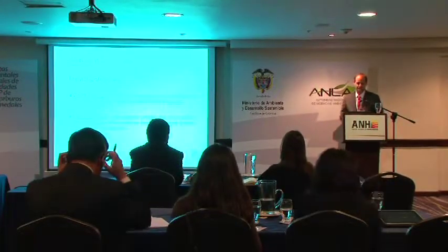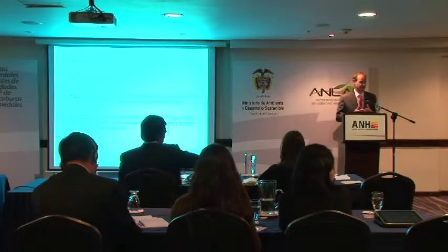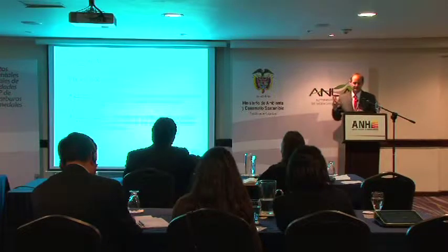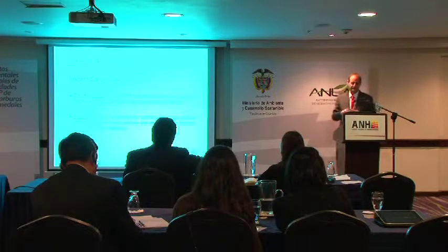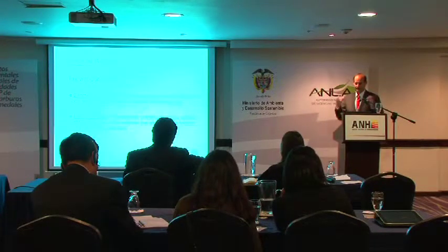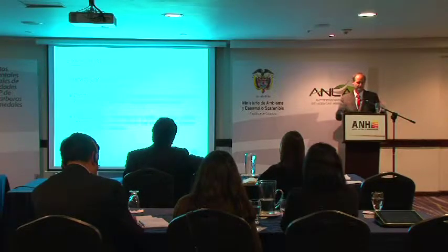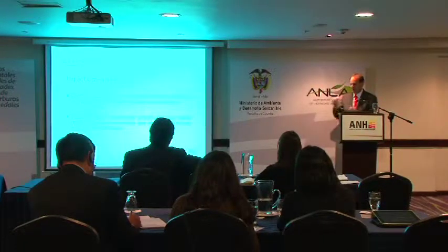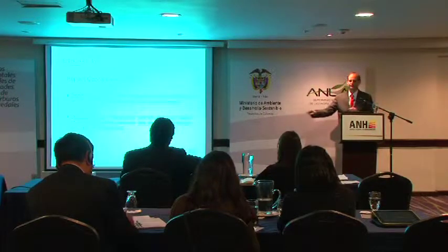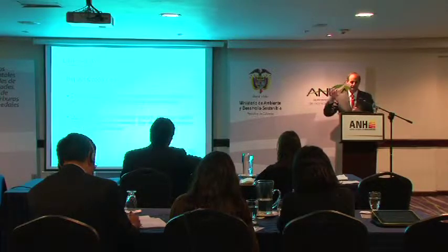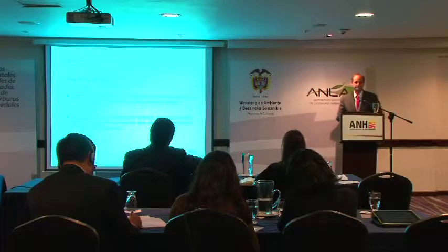So understanding first what those impacts are and what kind of impacts they are is the first step in the process. All impacts can really be divided into two categories: direct impacts and indirect impacts. Essentially for wetland processes, the direct impacts are those that occur within the boundary of the wetland and that will affect the wetland function. If I'm going to do a project in the wetland, what are the impacts that are going to directly affect that wetland? I'm going to build a road, I'm going to build a well pad, I'm going to do something that's going to affect the wetland right in the footprint of the project.